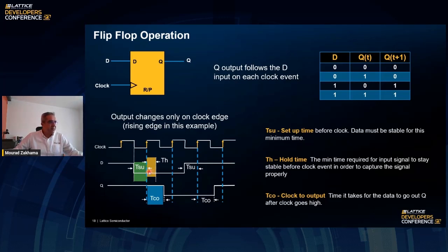So what is setup time? Setup time is the minimum amount of time that the data needs to be stable before the clock edge. The hold time, on the other hand, is the minimum amount of time that the data needs to be stable after the clock edge. So if we satisfy these timings, we should have a reliable operation of the flip-flop, and that has to be satisfied on each clock cycle and for each flip-flop that you have in the design.